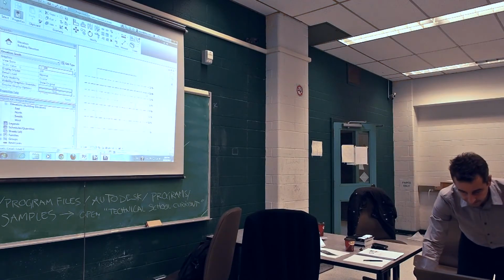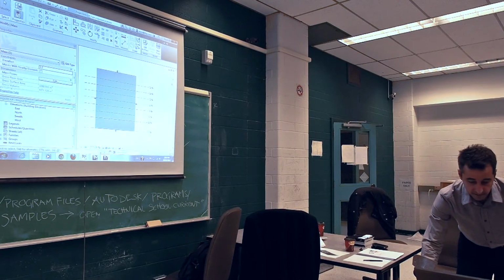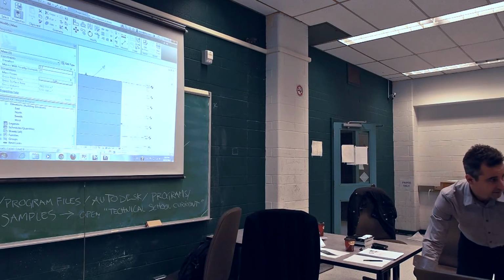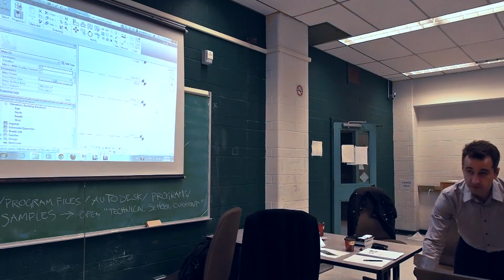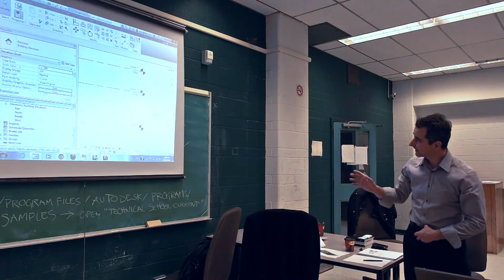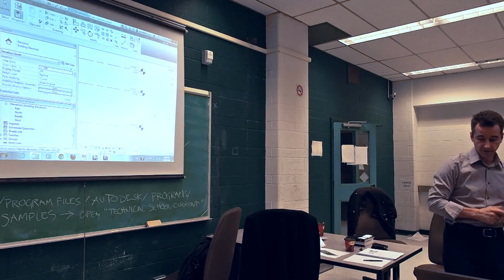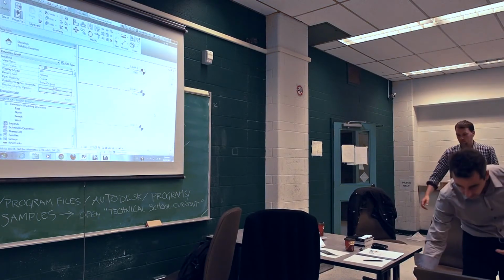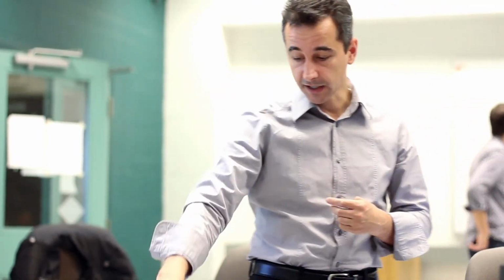You guys can go crazy. I'm going to adjust my shape. How do I adjust it? I just click on the form and I have these handles, and it's going to snap to this last level. One thing that is important, not for this exercise but for Revit: it's quite obvious on your screens that my first two levels, which are the default levels, are blue, and everything else that I copied is black. So what's the deal with that? Pretty much everything that you see in blue in Revit is going to take you someplace. So if I double-click on Level 2, it's going to take me to the Level 2 floor plan.